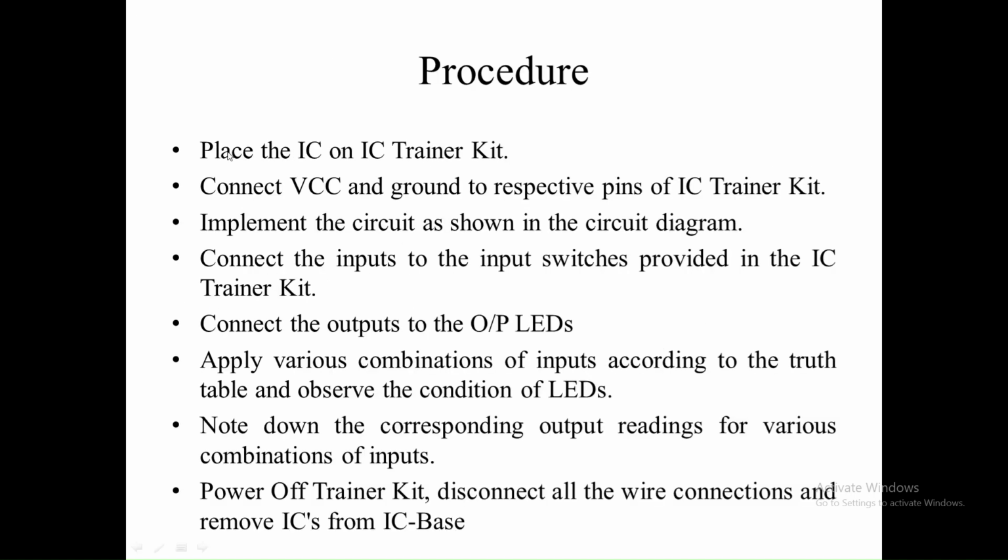Procedure: first, place the IC on the IC trainer kit. Second, connect the VCC and ground pins to the respective pins of the IC trainer kit. Third, implement the circuit as shown in the circuit diagram. Fourth, connect the inputs to the input switches provided in the IC trainer kit. Fifth, connect the outputs to the output LEDs.